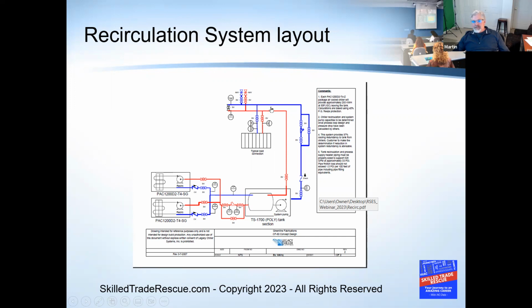So what happens is that big old chunk of heat, rather than getting pulled directly into the chillers, is going to mix like crazy in here, right? So they won't necessarily see as big of a degradation on that 45, because that hot fluid, depending on the flow and how much energy it is and the size of the tank, you're going to see a lot more stability right here based on the volume. So it's mixing with all that volume.